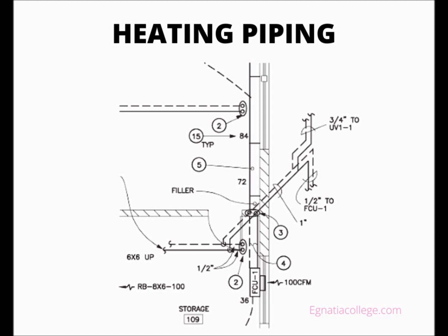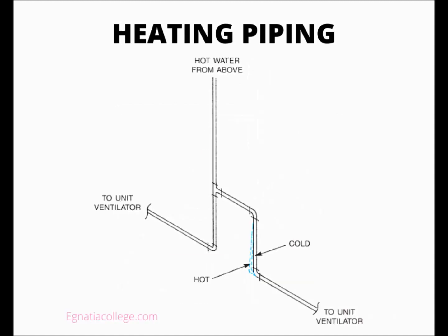The first thing we encounter is a valve, an elbow toward the top of the drawing, and then another elbow back to the right. Construction note 13 indicates that the pipes pass through a structural steel member. The line is broken for clarity through the area where ductwork is shown that would make reading the piping drawing difficult. Pick the line up again in the storage room 109. Next we come to a T where the pipe drops down to the level of the unit ventilator.